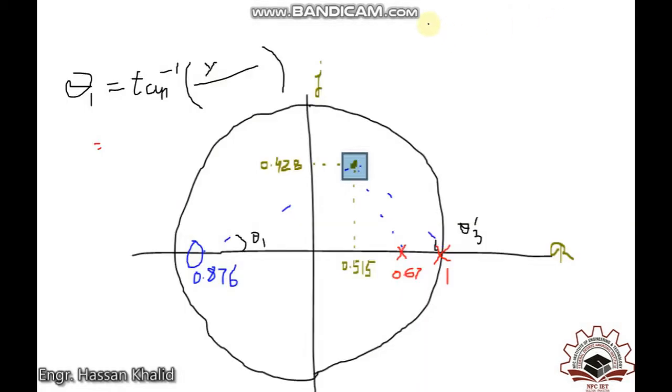Alright, now by definition we need to calculate the value of the pole that can be located, so you can easily realize in the denominator of the controller that it is equal to minus beta. So it is negative and will be lying somewhere around this location, but we don't know. So let's calculate it with reference to our given point, 0.515.